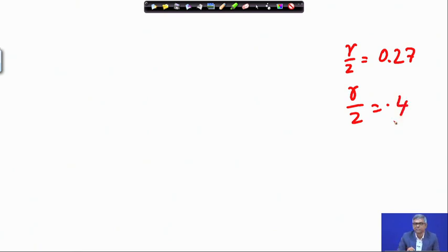Now, if I fix the depth equal to z, 2 meter, then r will be some value, suppose that is r1. That means, if the circular load area with radius r1 is loaded with intensity q, at 2 meter depth your intensity will be 0.1 q.